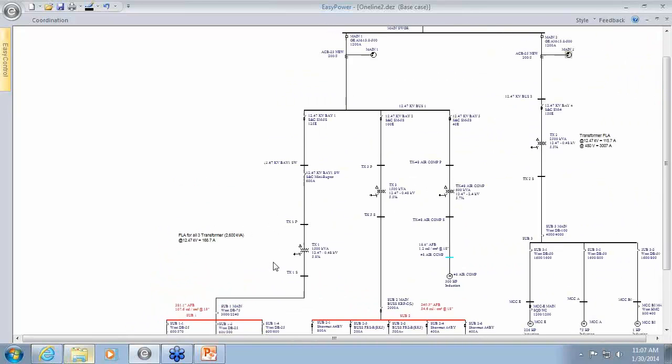So one thing that this facility considered was, because under normal operation this needs to be selective for reliability purposes, but they still wanted this to be lower if energized work did need to occur. Here they had a number of switchgear that had main breaker protection, but they also had a number that had fuse protection, and the fuses did not help with their arc flash.